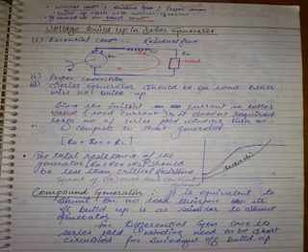So all the conditions are the same, everything is the same, because you know that on no load, the shunt generator and the compound generator are the same. Series flux is negligible on no load. Series flux comes into the picture with the load only. On no load, the current flowing through the armature and the series field winding is very small. So there is phi SH, there is phi SE. On no load, the current flowing through the armature is very small, so what is the series flux value? Very less, and this is negligible. So now what is the machine? It is nothing but a shunt machine. Everything is the same.